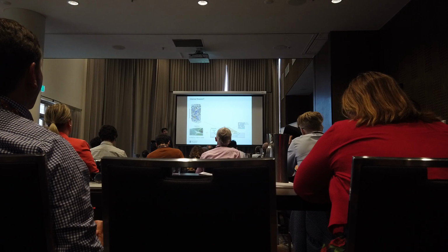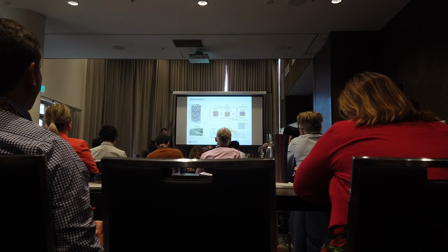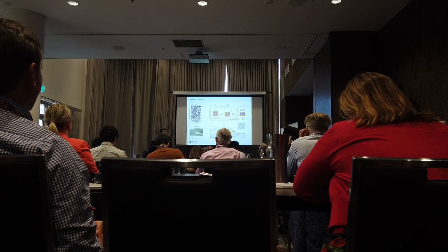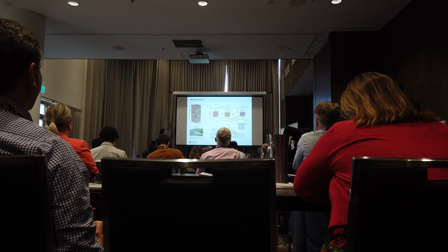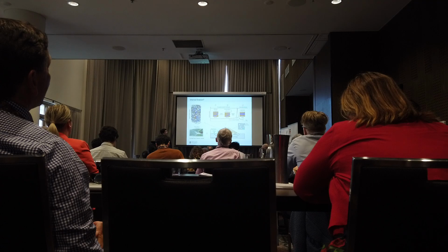And it's normally hidden, undetected. The challenge associated with internal erosion is, on one hand, it occurs at a very small scale. It would take months, years, or even decades to be able to detect the internal erosion. But at the same time, when the failure occurs, it will actually occur within a period of hours.